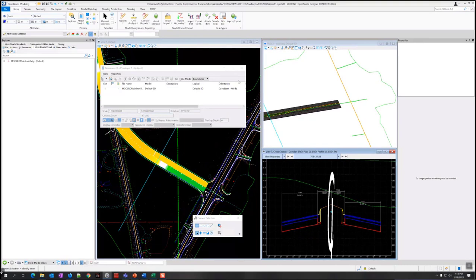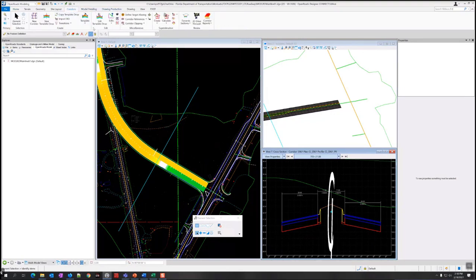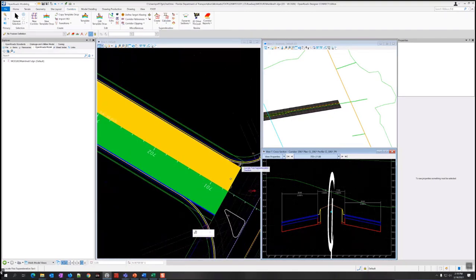We're going to assign the super elevation to the corridor. Close out of this so I can see my view over here. So I'm going to go here to corridors in the ribbon. And I'm going to go to the super elevation section, and it's right under the calculate menu. So click the drop down, and the very last option is assign the corridor. So after we've done everything else, we're assigning it to the corridor. It asks me to locate the super elevation section. So that's the green box that you have referenced in here. And then reset to complete.